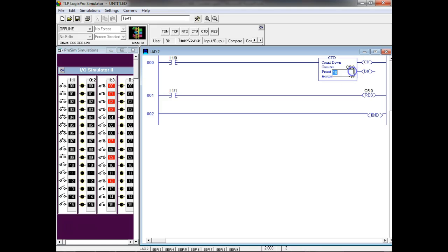No, we're gonna change the accumulator. We're gonna set the preset to 0, and then we're gonna set the accumulator to some negative value. Or did I do that, Mark? No, I think. No, that ain't gonna work. Yeah, so the preset is gonna have to be a negative value, and then we can set this to 0, right? That makes sense? Okay.